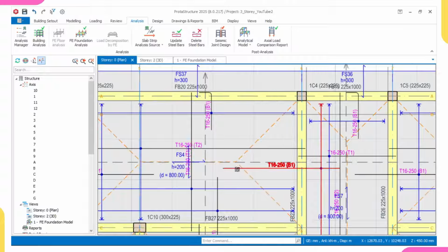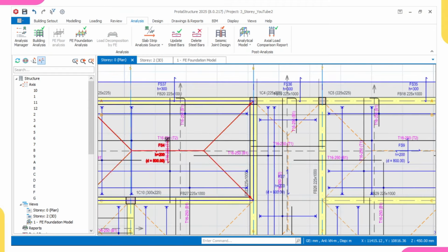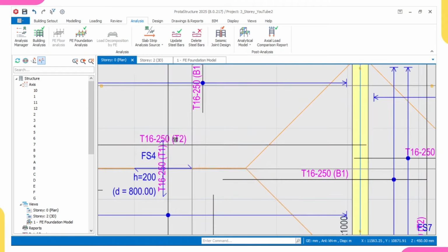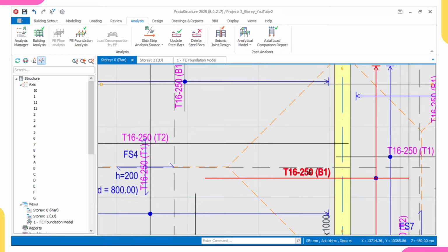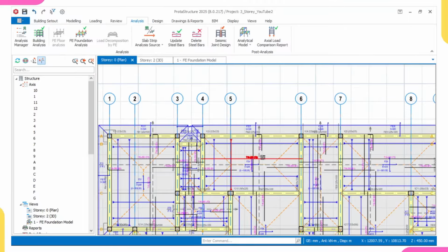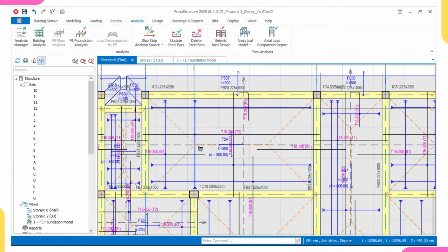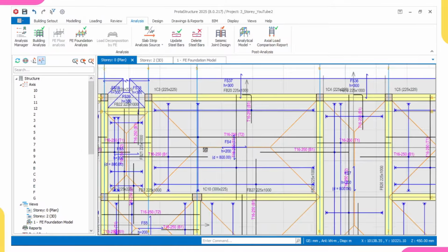What we normally provide as moment reinforcement in a normal slab, the top reinforcement, they put as bottom here. And what we used to place at the bottom in a normal slab, they put as top. That is correct, but I'll explain more when it comes to detailing. If you want to understand it more, watch the video we are going to do about this beam raft detailing. It is for free.